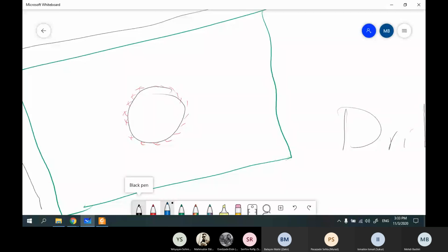What should you do? You should consider the hole like this. At first, you may see that this is your hole with diameter d. But as I said, because we have micro cracks here, we should consider the diameter this one, not that one.